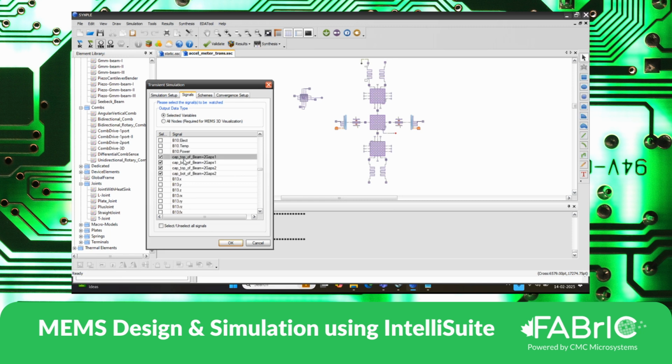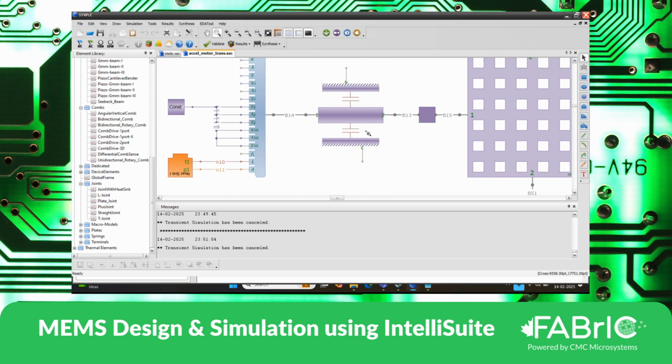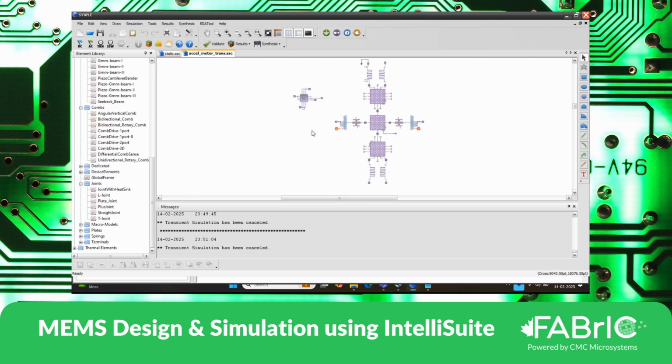So we are trying to get the capacitance of the bottom plate on one side, and the top plate on the other side. So we have two-sided capacitance. Here I'm trying to extract this side of the capacitance and this side of the capacitance. Similarly, this one and this one. So we get 4 discrete capacitance outputs. So let me run the simulation.